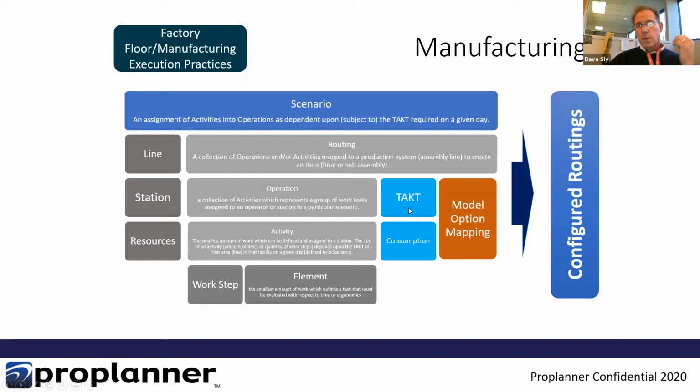When we look at the process side of that off to the right, we're looking at takt time, which essentially represents the pace of the line, how often a unit can come off the line on average. That's going to vary a little bit if we have a lot of mixed model production where some products take a lot more time than others. We may have the lines penalized quite a bit in terms of efficiency when we have that kind of variability. We try to keep that out of there. But the reality is the takt time represents that overall pace of the line; the longest cycle time that we incur in producing the products in that routing is going to drive that takt time pretty heavily.